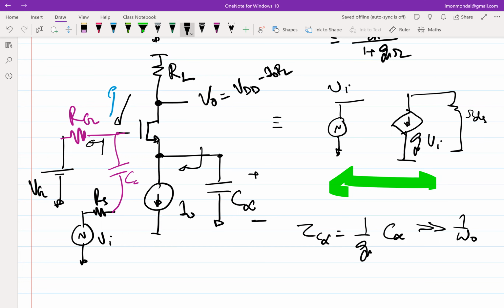If I take you back to the analogy of water, if this transistor is a tap and water flow is the current, then C infinity is a bucket. It's a huge bucket with a lot of water level, right? So you put in small drops of water, it doesn't really change the height. So it's equivalent to that. C infinity is a capacitor which stores charge. If it's large enough, a small amount of current change won't really change the voltage across it, right? So that's what is happening.